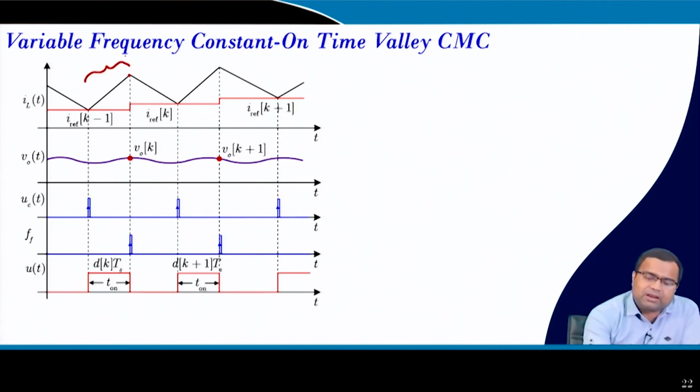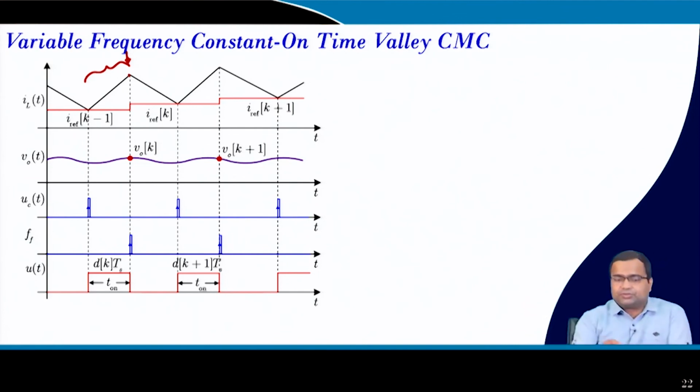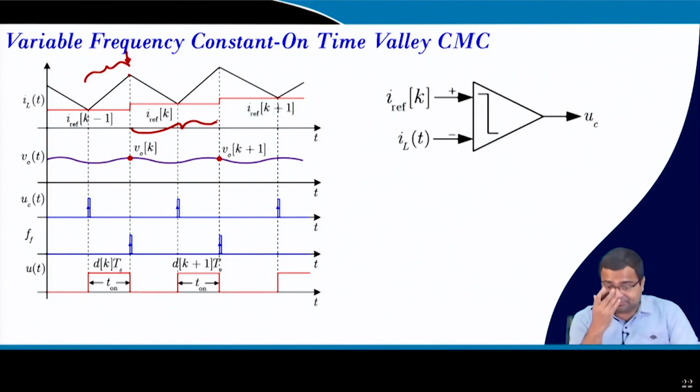So, once the timer almost finishes the timing, then you can send a sampling command, and then after a short time you actually turn off the switch. That sample takes the valley current, and then you can do the regular valley current operation, in the sense that the valley current remains fixed for the whole duration, and again it is event based sampling, one sample per cycle, and you can stabilize and get a wide operating range.